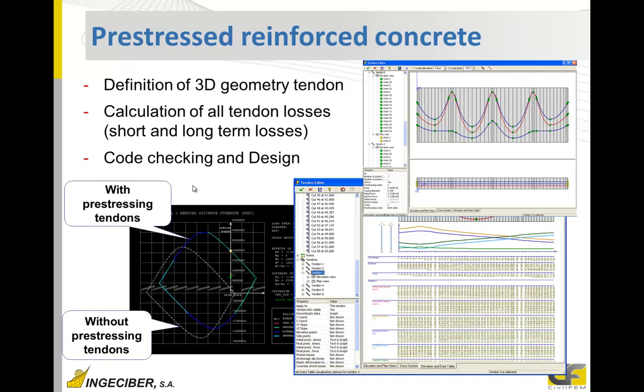So well, the next tool is applying prestressed reinforcement tools on the model. We have different ways, three main different ways, to define tendons and to apply these tendons to the model. The most detailed one is through this tendon editor, which is a browser you open, and you can define tendons by points and the layout inside the concrete walls.